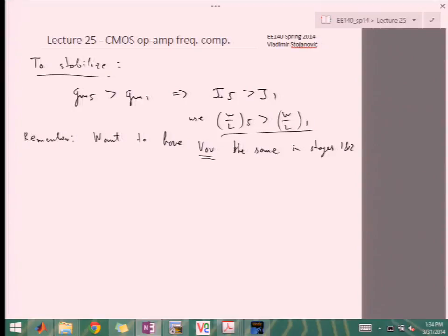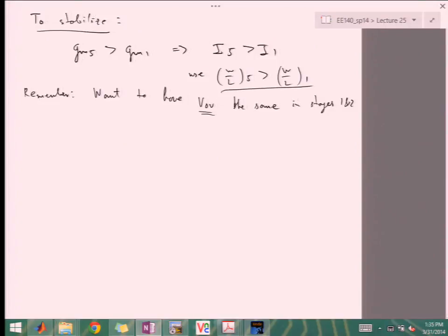Just intuitively, when did we worry about KVL loops on V overdrive and VGS? Okay, swings, one thing, but here you would just get a different swing range. It wouldn't necessarily enforce that all the V overdrives are the same. When did we worry about all the overdrives being the same? Yeah, the systematic offset. We wanted to have the same overdrives in both so that the current mirrorings end up being the same, right?